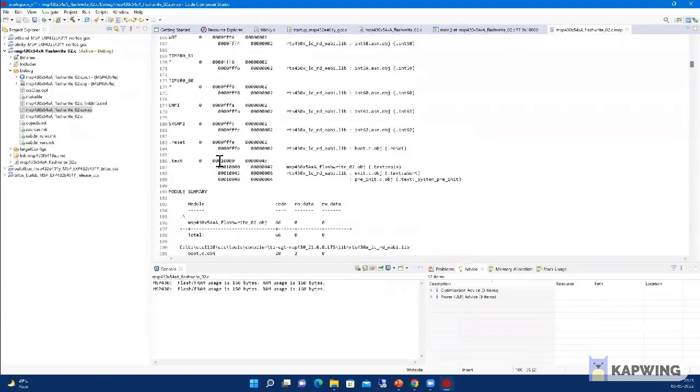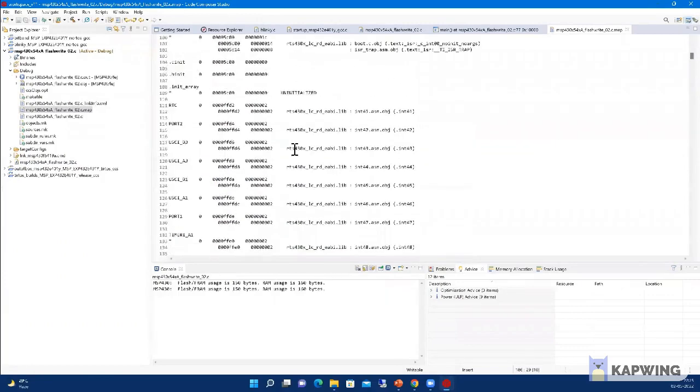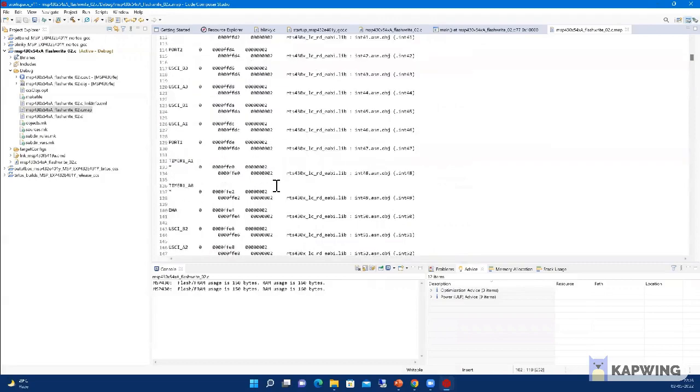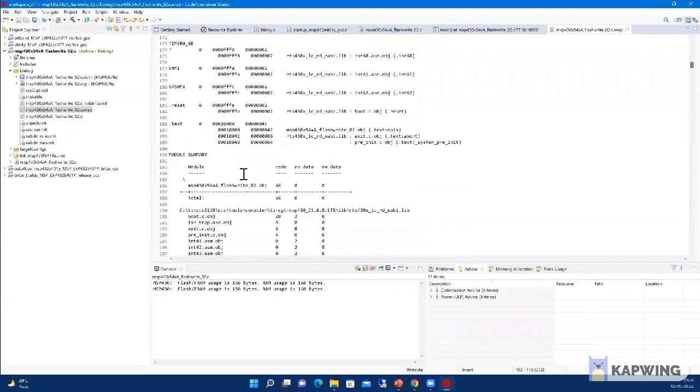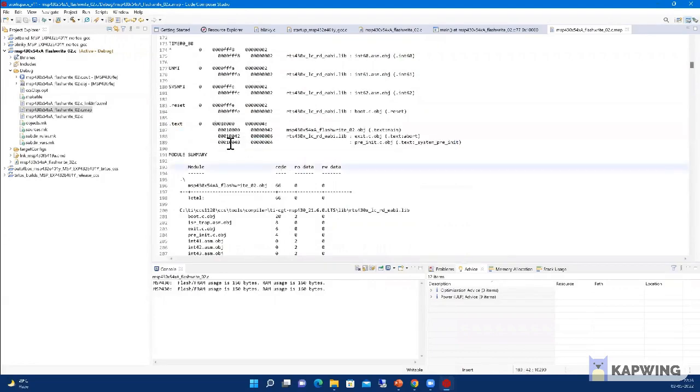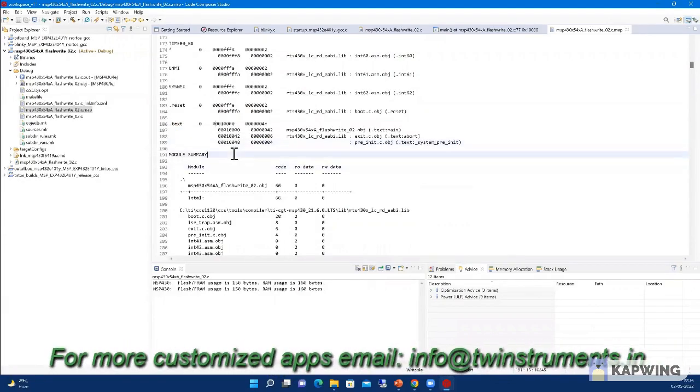This is the initialization part, the boot.c file, and that is our trap. After that, hex value 10000 is the actual memory where your code is. So just remember, if you're using the upper part of the flash, remember to place it above hex 10048. In that way, you will never clash with your existing flash or code.